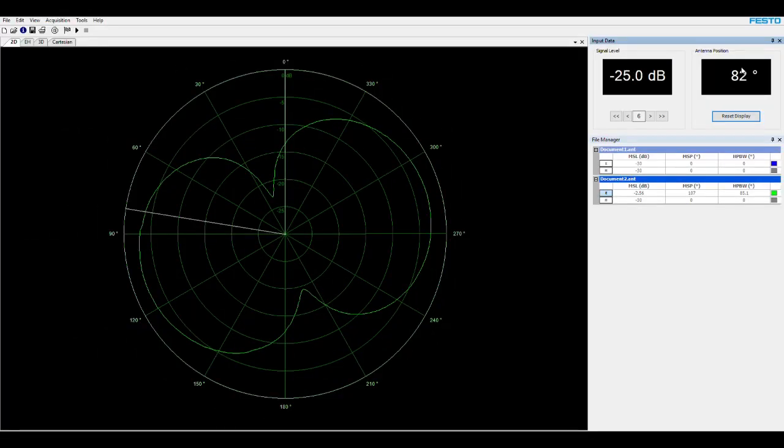Okay, in the previous measurement we had our E-plane cut in the co-pol case. Now we've rotated the transmitting antenna by 90 degrees. We kept the antenna under test exactly the same. Now we are gonna collect the cross-pol E-plane cut, and for that, we also keep the 6 dB software attenuation the same. And we're gonna start our measurement.